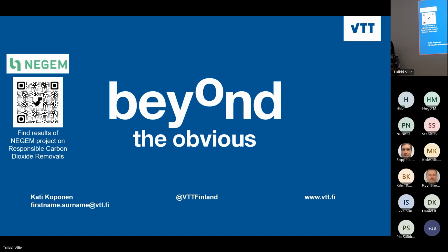Yes, hello, good afternoon. Cyril here. The question is, how flexible are DAC applications in terms of energy demand? If you want to make DAC systems flexible, you would need a thermal storage system for that, in the sense that when you start heating up solid sorbents, the heating has to continue until you reach the desired temperature. We have experienced previously that when you make it dynamic, you actually have a lot of losses in the system.